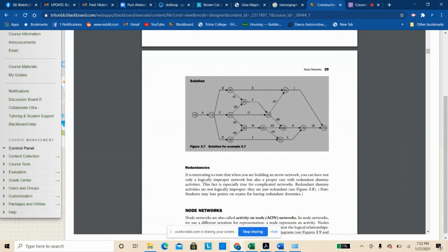This was more useful back in the day. Basically, when they were doing all these network diagrams and tasks and logic diagrams, computers weren't especially used in construction. They would be used for logic and programming. This was their way to mathematically compute what the critical path would be when you have a really complicated set of relationships and interdependencies.